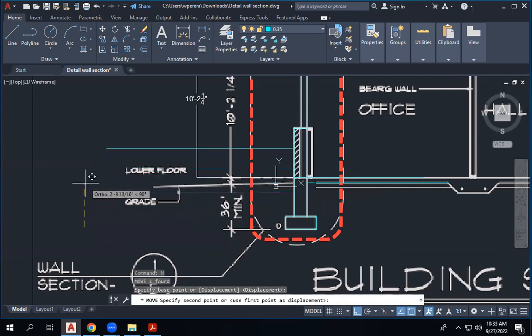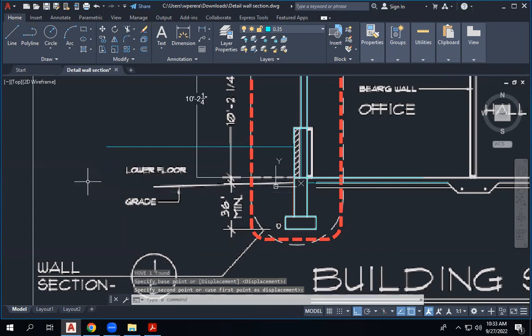So let's consider it like this. I'm just teaching you in the actual site condition. Now, if someone walks here and steps down, then this part cannot be timber or any other material. That material needs to be concrete, because the soil is pushing on this, and also the water inside the soil affects the material here. So the foundation should go right up to this point if you have a condition like this.